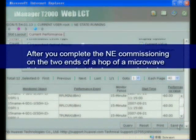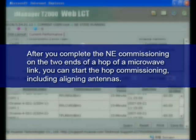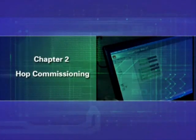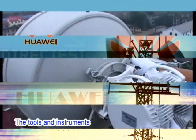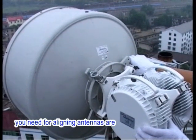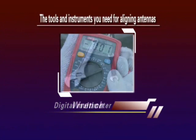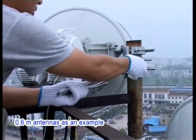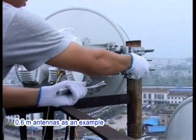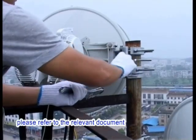After you complete the NE commissioning on the two ends of a hop of a microwave link, you can start the hop commissioning, including aligning antennas. Chapter 2. Hop commissioning. 1. Aligning the antennas. The tools and instruments you need for aligning antennas are BNC cables, digital multimeter, and wrench. The following operation considers aligned 0.6 meters antennas as an example. When the antenna is of a different diameter, please refer to the relevant document.